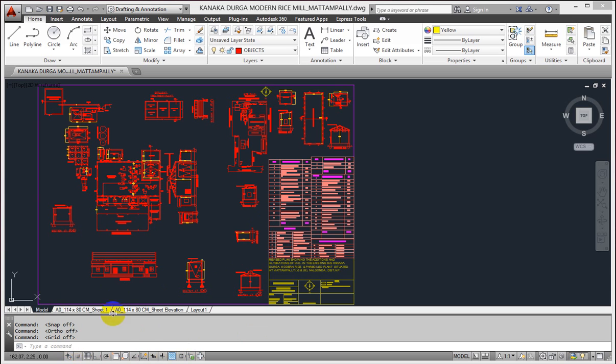In this tutorial, we are going to look at drawing aids tools in the status bar. Below the command window is the status bar. The status bar gives you information at a glance about the state of the drawing. For example, the coordinate readout here. This is x-axis, y-axis and z-axis. Notice when I am moving the cursor, those readings are changing. The tools in the status bar offer aids to the drafting process. You can toggle any tool on or off anytime in your drawing.